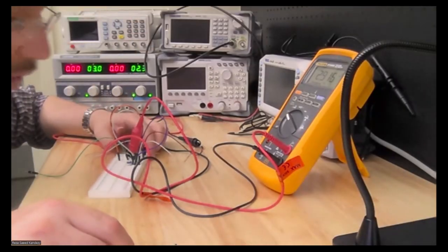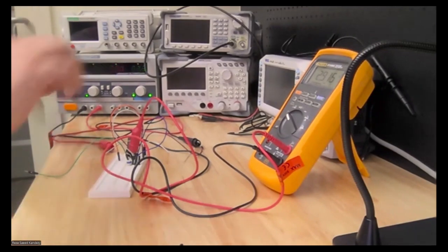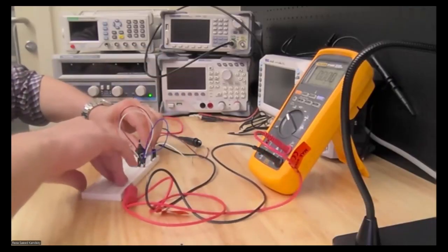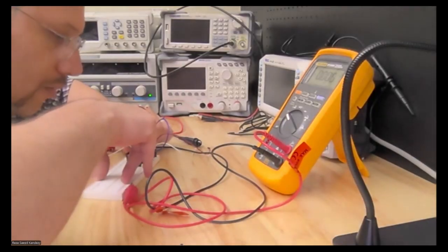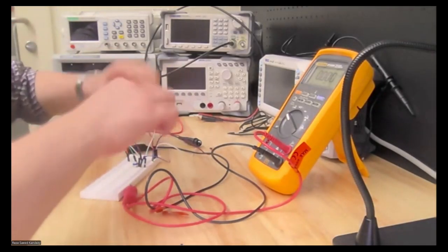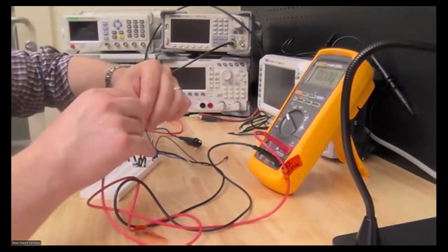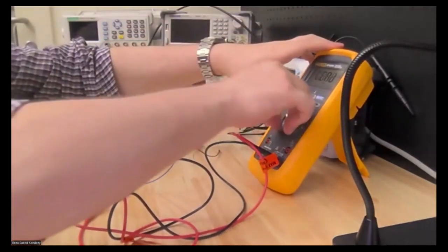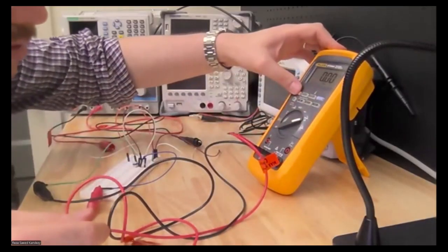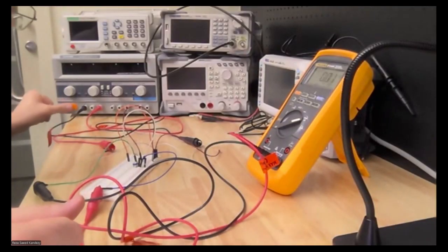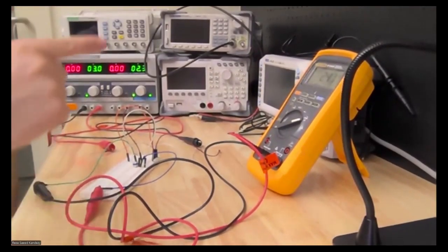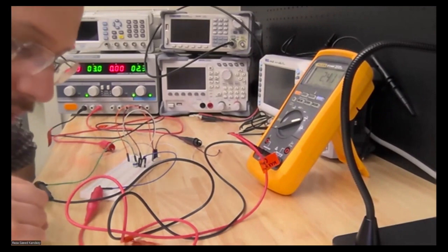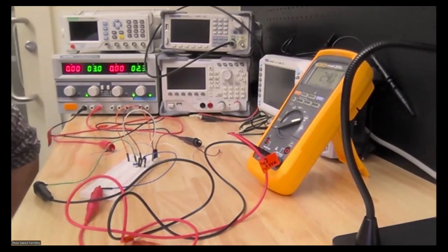So now I am on 2.9 volt. Okay. Now for this specific volt, I am gonna measure the collector current. Remember, it should be DC. Apply the voltage. It is 2.4 milliamp. So this is the second set of my measurement.